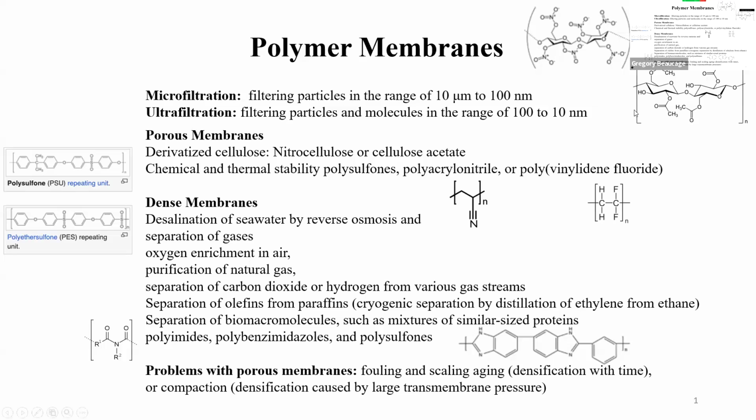So anyway, hydrophilic is good if you have a porous membrane. If you have a solid membrane, then you have to worry about, does the stuff dissolve in the membrane? If you have a membrane that's like saran wrap and it's hydrophobic, it's not going to transport water, right? Because the water can't absorb into it, even though water might have a huge diffusion coefficient inside the film. Once it gets in, it can walk across it, but if it can't get in, then it's not going to transport. So it needs to open the door and get into it, and then it has to walk across it.